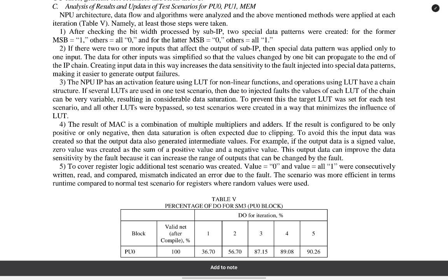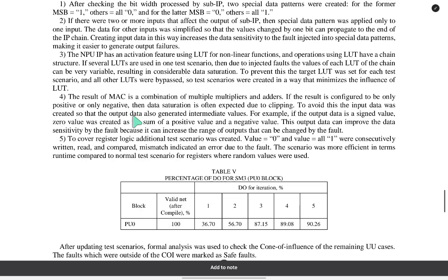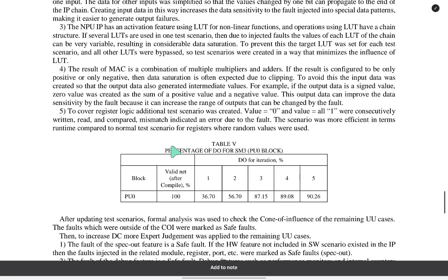To cover the register logic, additional test scenarios were created. Value 0 and value 1 were consecutively written, read, and compared. This method indicates an error due to the fault.